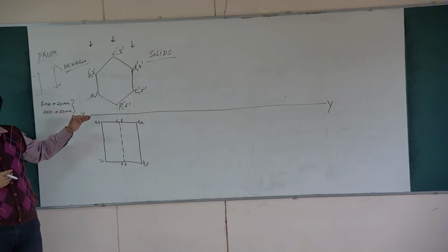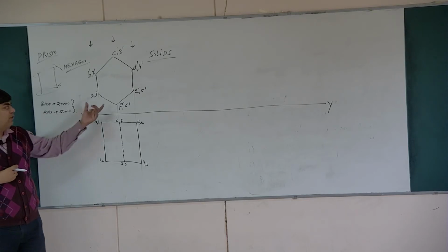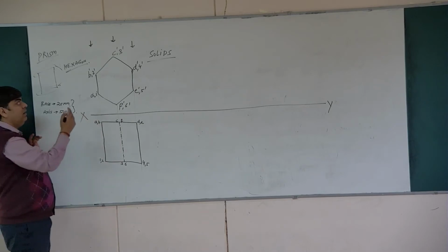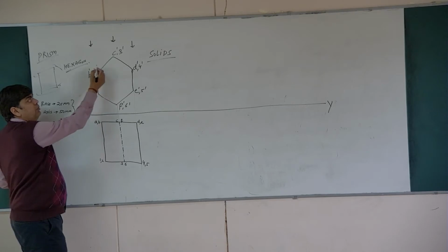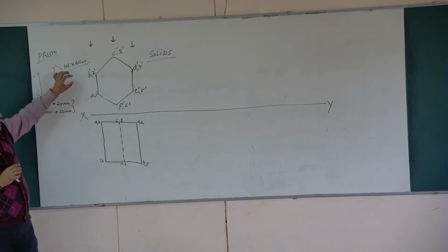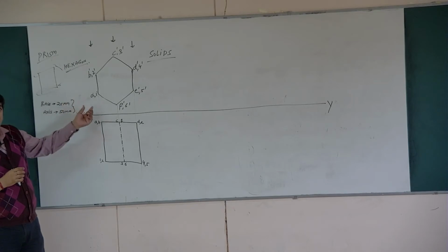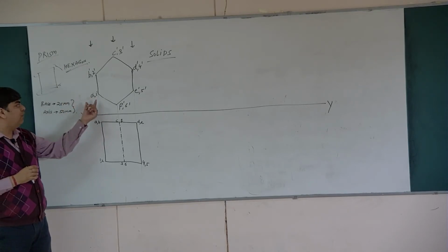When the points which are nearer to xy, when we are viewing them, they will always be hidden because we cannot see them clearly. But on the other side, you have the points B2, C3 and D4, they are clearly visible. So, always remember, when a clearly visible point is superimposing or overlapping your hidden point, then we always have to show it as continuous.